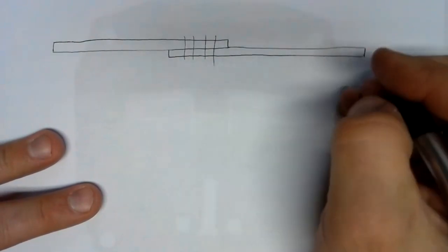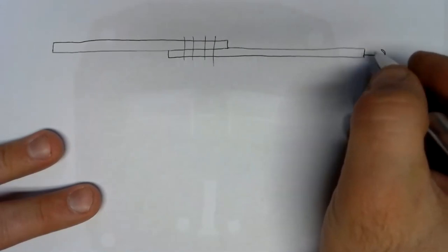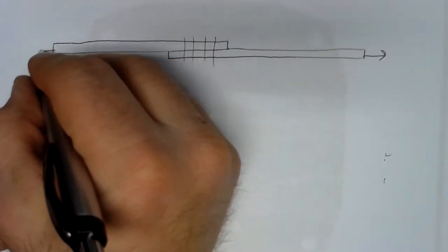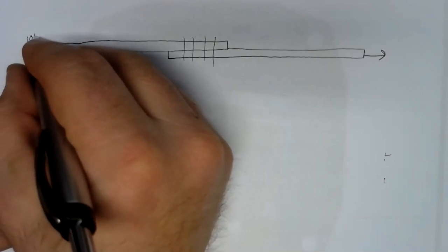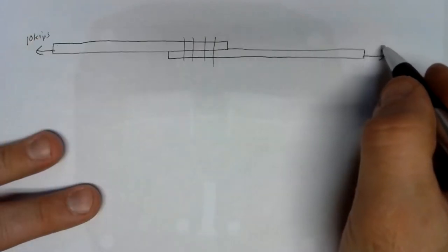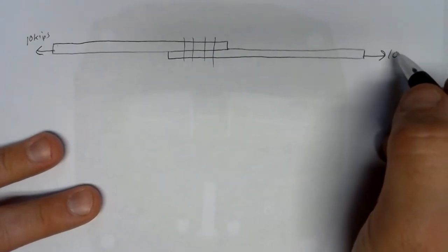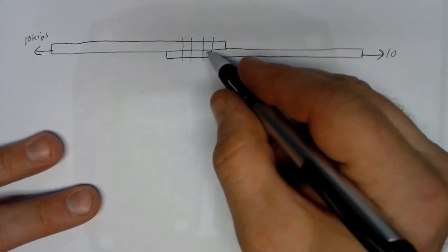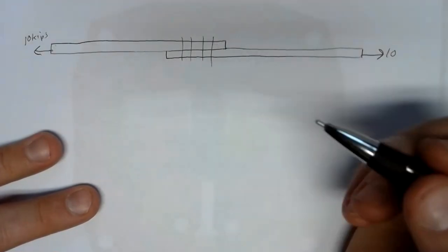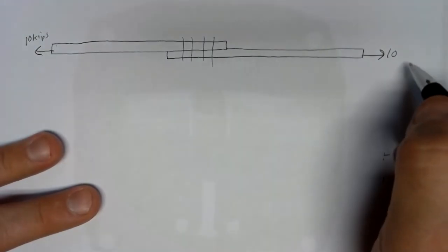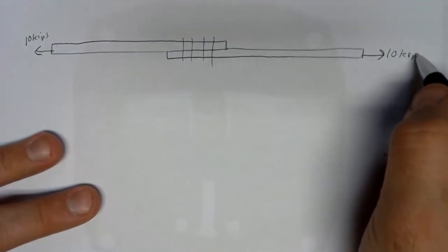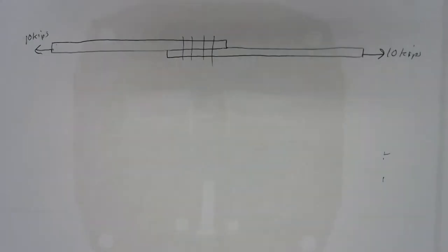Now, those of you who've been through sheet metal know a thing or two about minimum edge distance and pitch and transverse pitch and all of that. As long as we're assuming that we are above those values, so our rivets are not too close together and far enough away from the edge that we don't have to worry about those values. When you get below those numbers, you're making the rivets interact with each other.